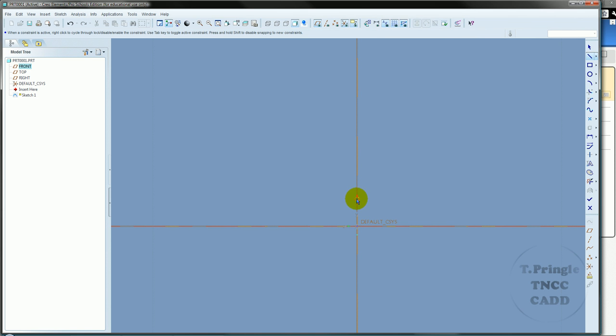And I'm going to start this part by just drawing a line straight up, in, up, over a little bit, down, and I went a little bit too far down and accidentally placed a constraint that I didn't want to have in there. So let me go back to the line command again, and we'll bring this over here. I want to be very careful not to have any automatic constraints placed, just because that's not going to be good for the overall part.